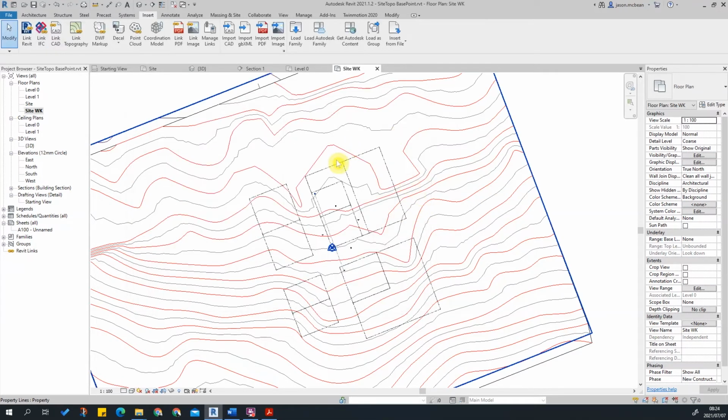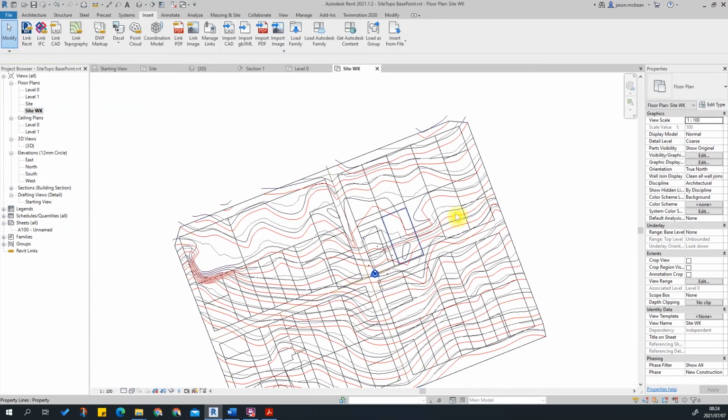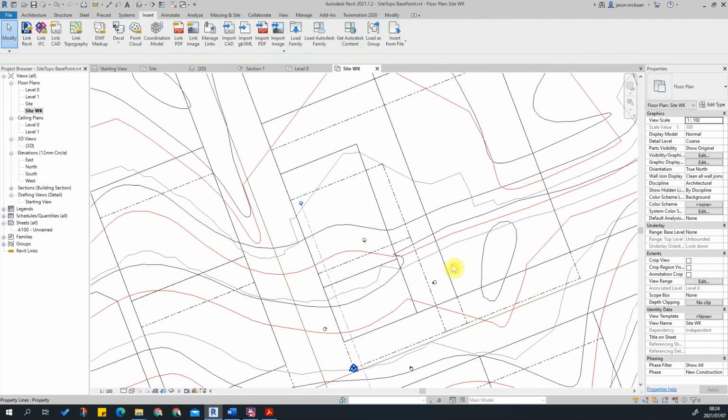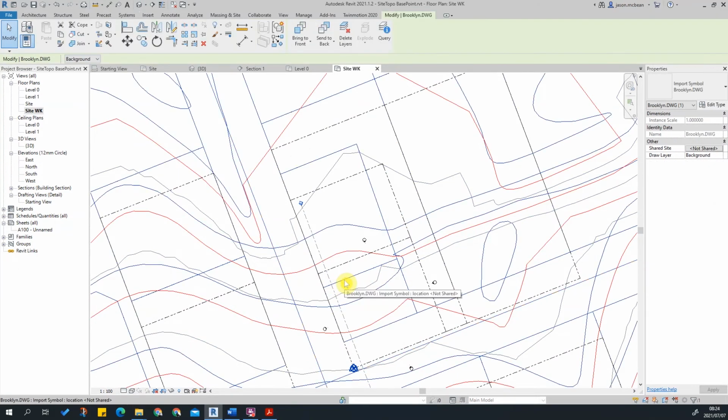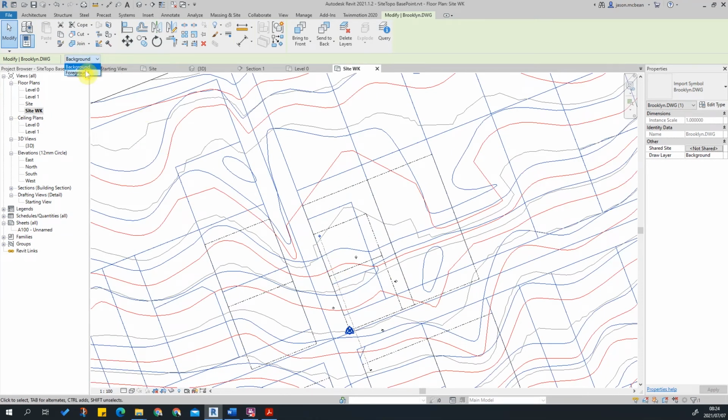You won't see the drawing initially, just because it's a drafting element and is always beneath. So you might have to go and select that element first. I've selected the wrong object, so let's find it, here it is, the site information tab. Now that I've selected the site information, sometimes it's pinned. In this case, it's not. And you're just going to move everything to foreground.